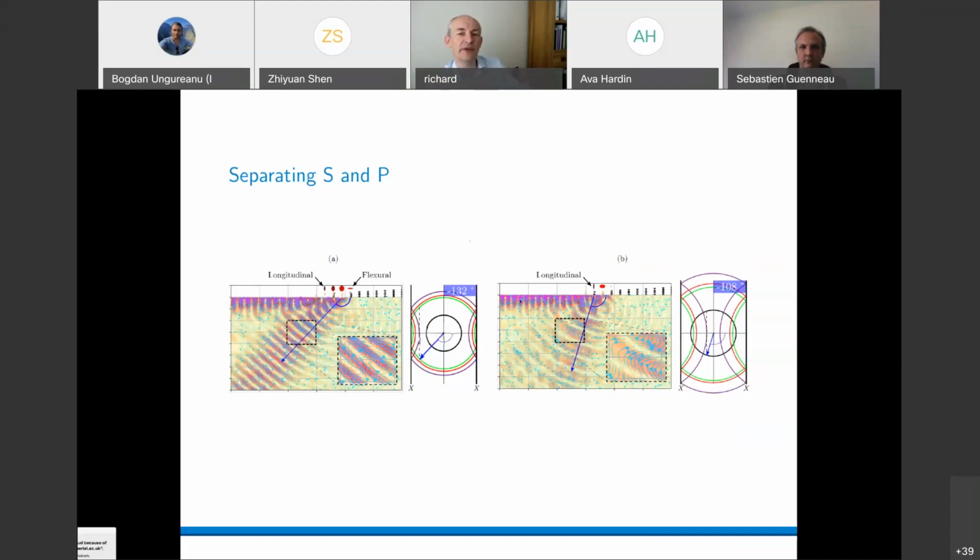When we do a forward propagating one, but we change the frequency, and we look at this surface, we see that in this particular case, the resonance that we care about is the longitudinal one. We get the flip back. In this case, our vertical line hits the compressional mode, and we have our surface wave come in, and it's converted only into compressional and along a direction of our choosing. So we're beginning to make a tunable, multifunctional elastic surface. It's fun. It's nice that it works, and it's also nice that we can take this idea of what's called Umklapp flip-over processes from a different piece of physics. So that shows us that we can separate our Rayleigh wave into shear only and compression only.